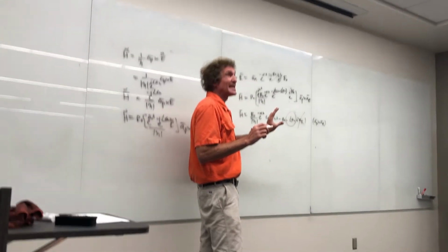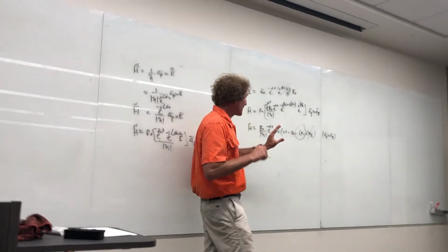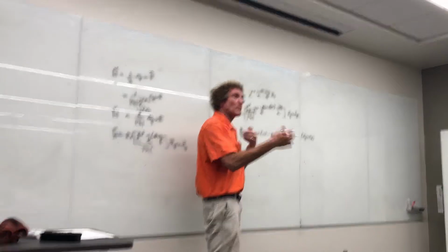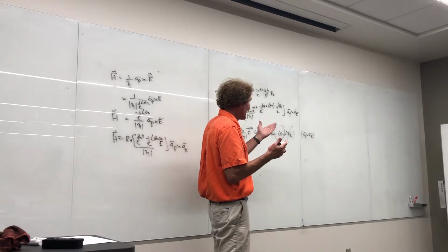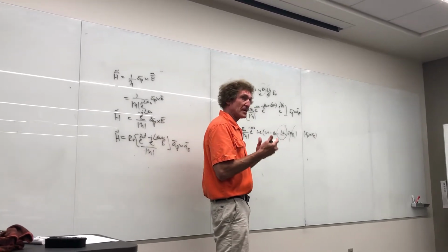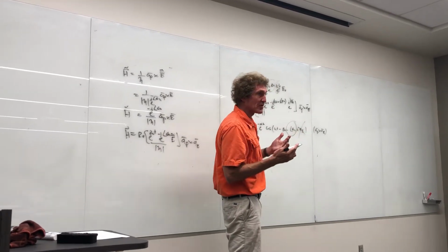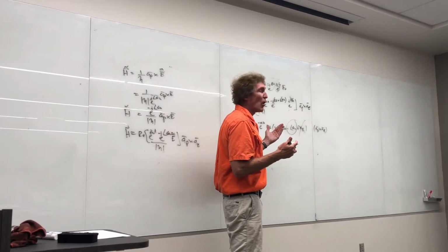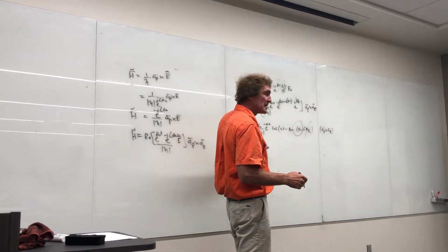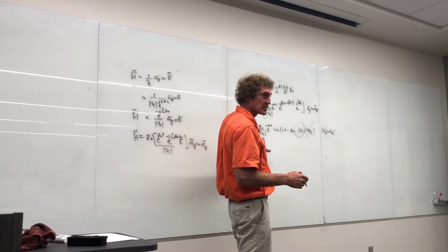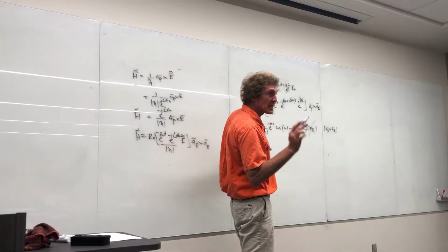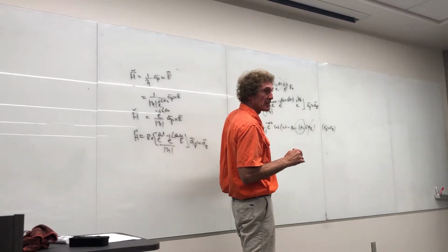And instead of being 90 degrees out of phase, it'll be out of phase by less. The H field will always lag, or the current; you think of it, H is in amps per meter, E field is in volts per meter. Well, the H field is really current per meter, and it will always lag by the phase angle associated with the intrinsic impedance. And the most it can lag by is 45 degrees, remember that.